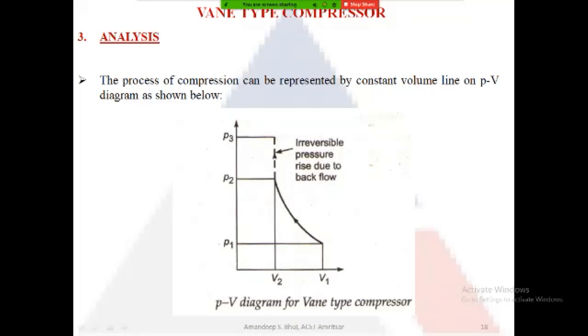So pressure increases, volume decreases. This compression is because the trapped air is being compressed against the casing. This compression is a parabolic curve, and it is assumed to be adiabatic, that is, no heat loss is taking place; the heat loss from the system is zero.